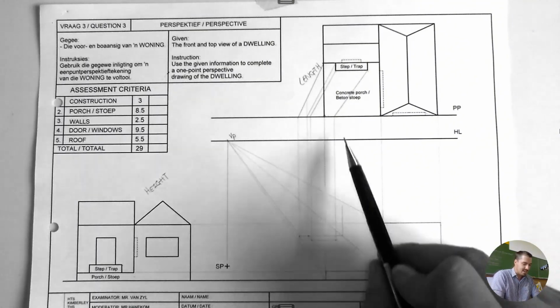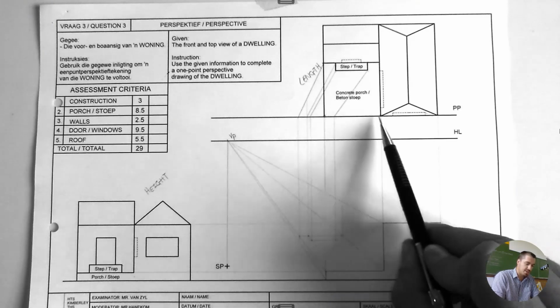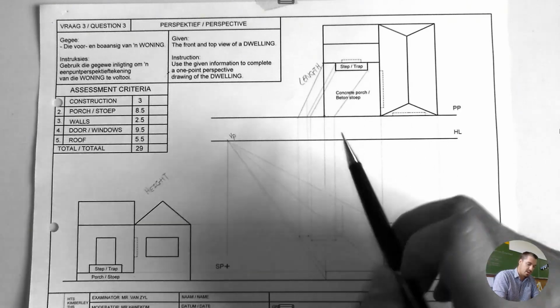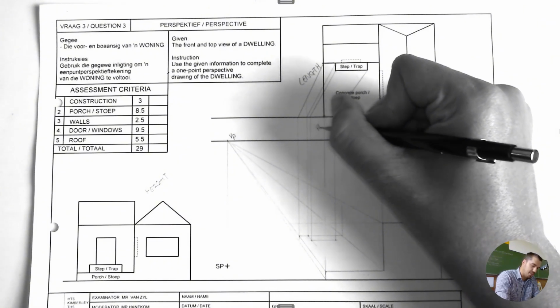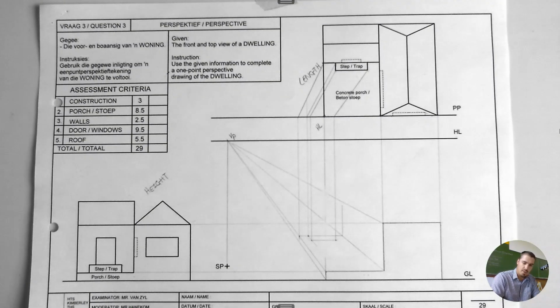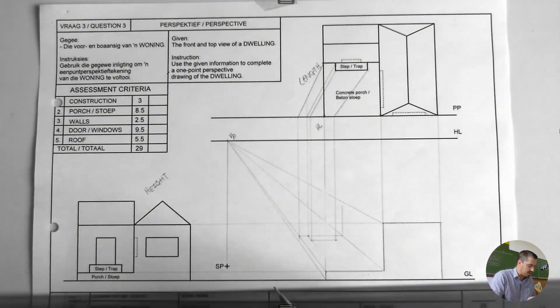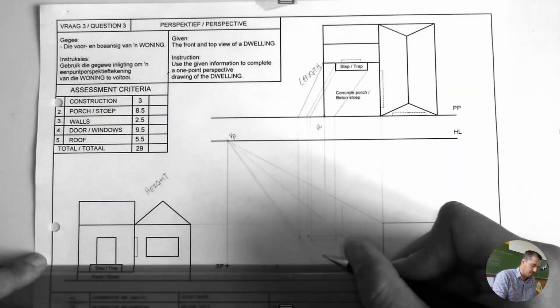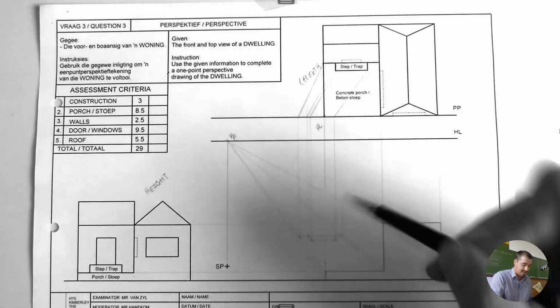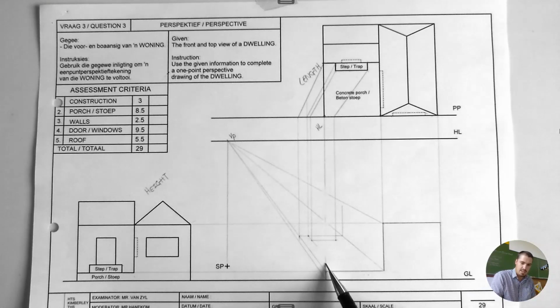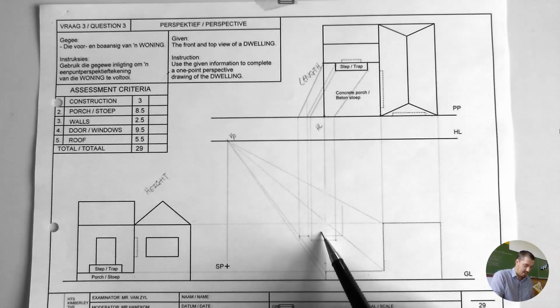the lines that already touch on the picture plane like these are called height lines. That's why I can project them down from the start and actually start getting the image, because I can directly measure the height onto a height line, and then I have it. So I now am going to take the step onto this height line, right? There's the height for the step.